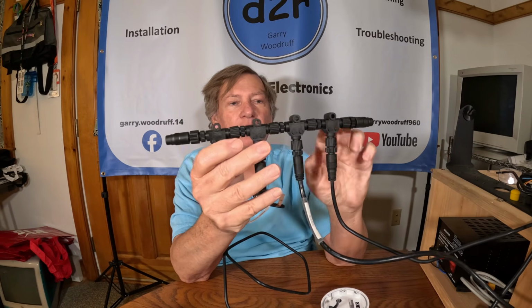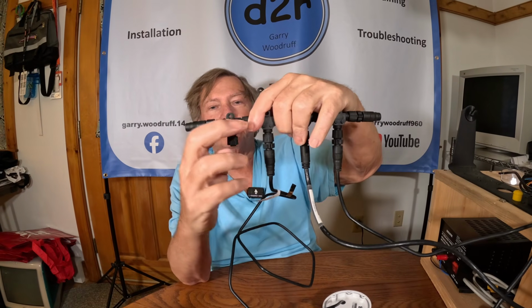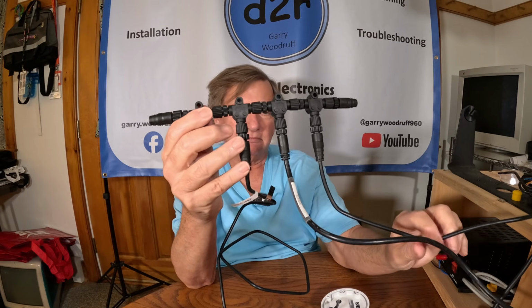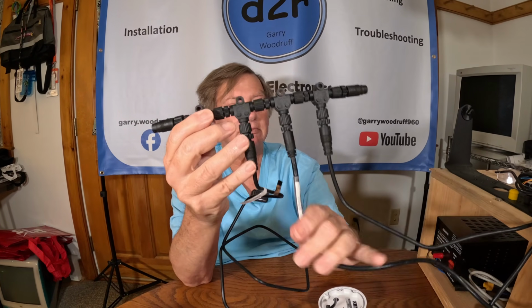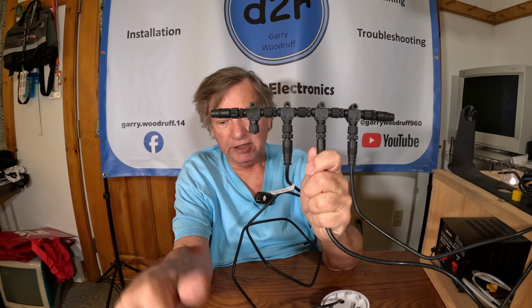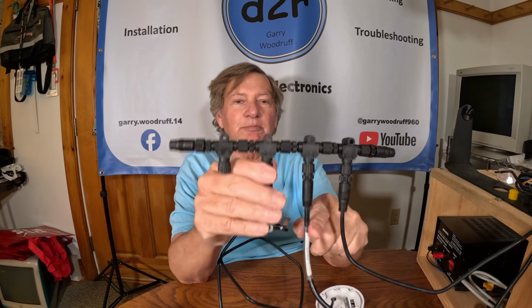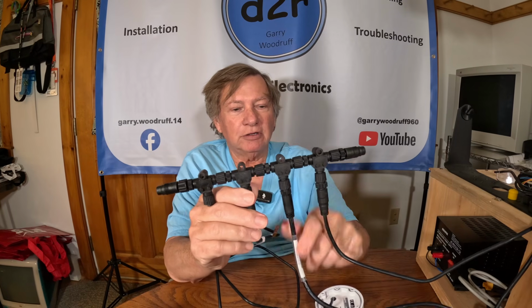And it should all be coming off the top of the T. So this is considered the T portion, right? On this NMEA bus I have built up on my test bench, this line right here is my power node. The NMEA bus needs to be powered up. The Ethernet is powered up by the internal circuitry in the units themselves. But the NMEA 2000 uses a separate power node, okay?